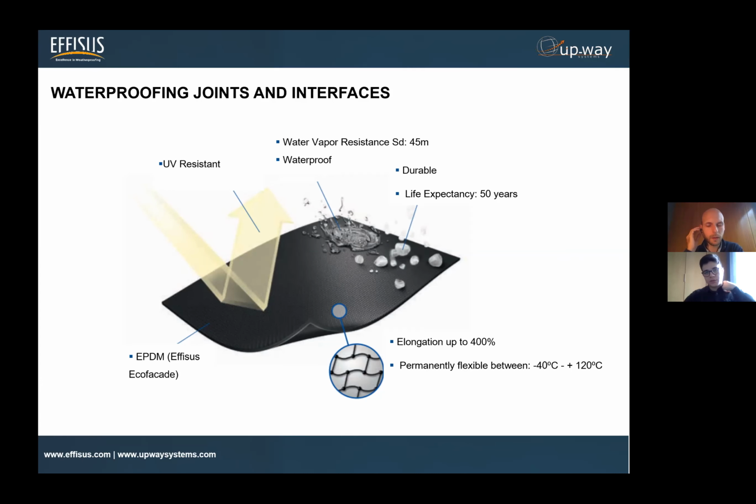Absolutely. As you mentioned, most of the people are aware of EPDM. It's a material that's been largely applied. Firstly, it's a rubber material. It's been applied largely in roofing, and later on we adapted it to this type of interface. It's a material with over a 50-year life expectancy. And we mentioned life expectancy: in this case, we also have data proving that this is not based on accelerated aging tests. So it's been in the market for over 50 years.